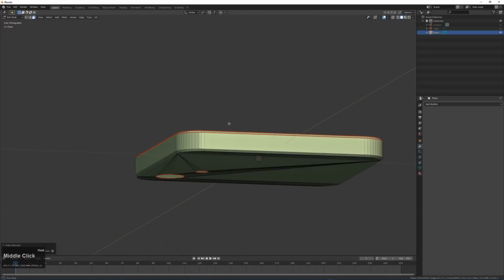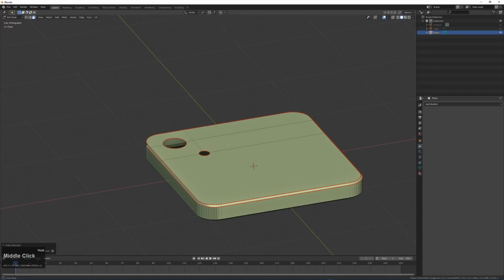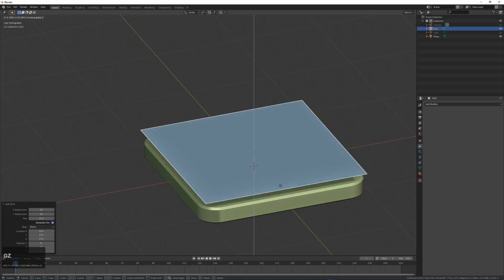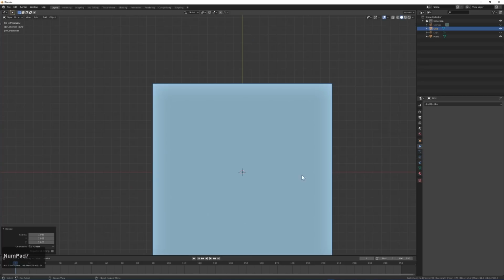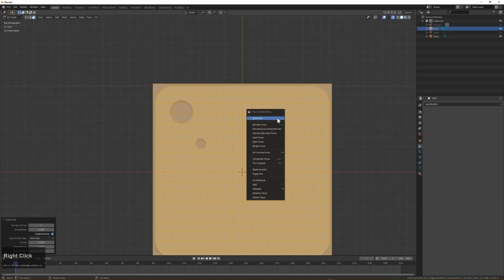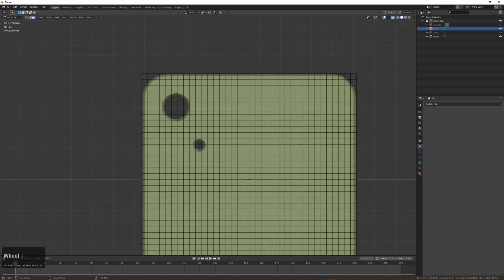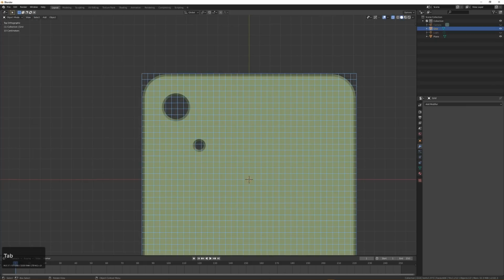And all we want to be exposed is the geometry that we're going to be dealing with very shortly. So let's just Shift A, and we're going to add a grid this time. We're just going to move that up, scale it up a little bit, and this is what we have for a grid. And to be honest, I'm going to want to subdivide that maybe 2 more times by just right clicking and choosing subdivide. And after getting a couple of subdivisions in there, we'll press X and we will remove only faces. So we have this edge matrix now, right?